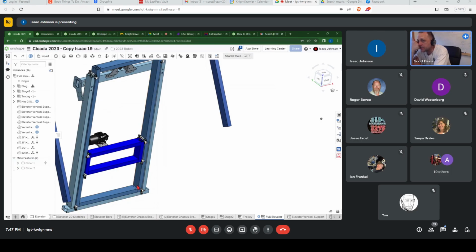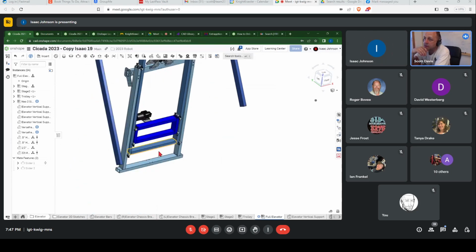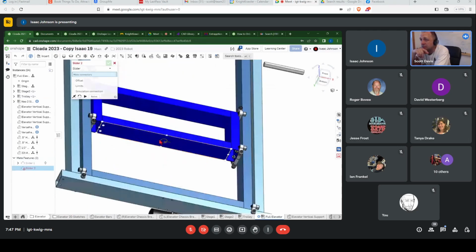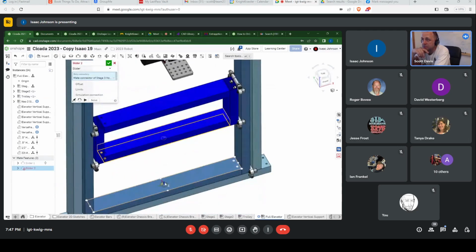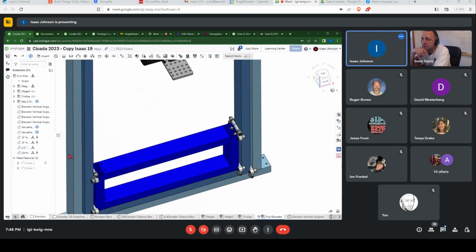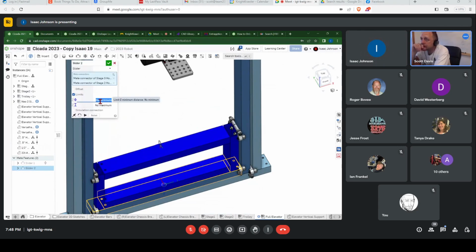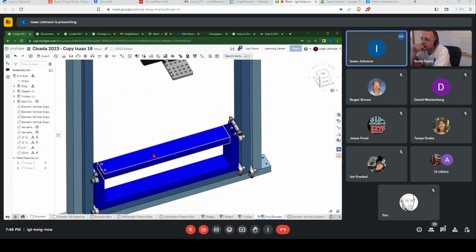I don't remember how big our elevator is. Is it 48? Oh, that's pretty good. So we probably would never want our elevator to go any higher than 30 inches. And in fact, we have it at 0, but we probably would never want it to bottom out. We'd probably want it to stop an inch before the bottom, because you just destroyed your bearings.